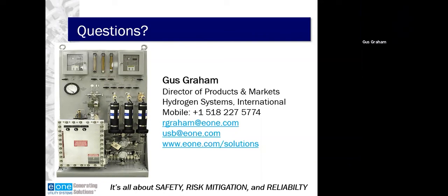Now that can be programmed differently in the control room, but typically it matches. So if our low purity alarm or warning is at 95, the increased scavenging mode would kick in at 95%. But again, that can vary from plant to plant.